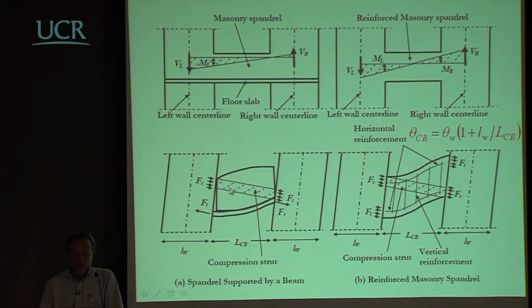Well, if you have a floor here and you have a coupling masonry element here, an unreinforced masonry element here, what happens is that you do not have any tensile capacity here, you don't have any tensile capacity here. So this case is essentially the case that I was describing earlier for a vertical wall just rotated of 90 degrees.